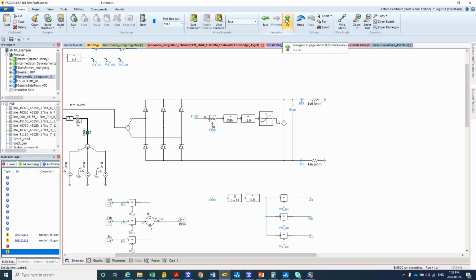Important features of components of an inverter, specifically the DC link, the chopper at the DC link, are always represented in EMT type simulations.